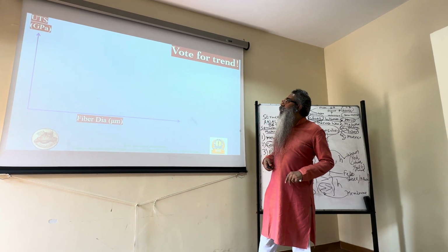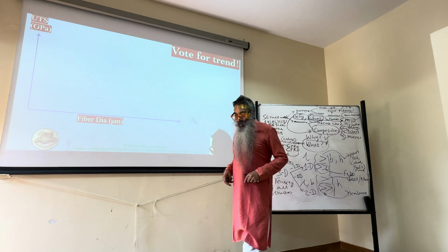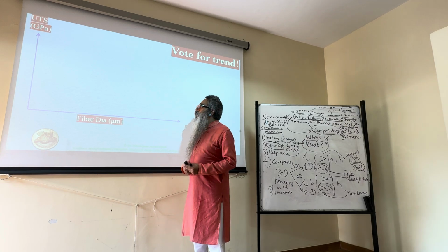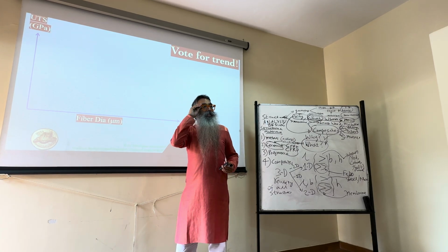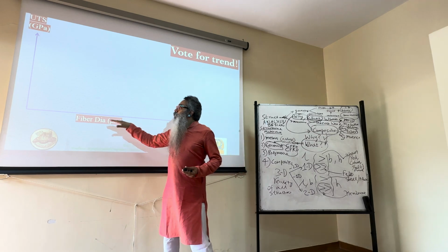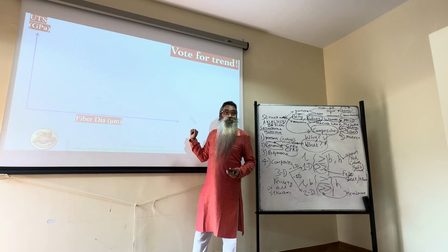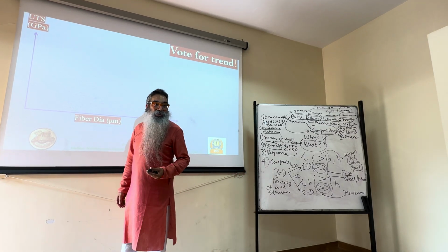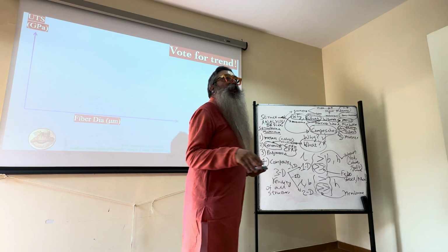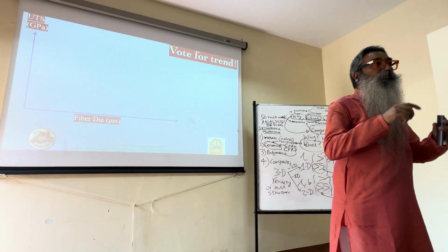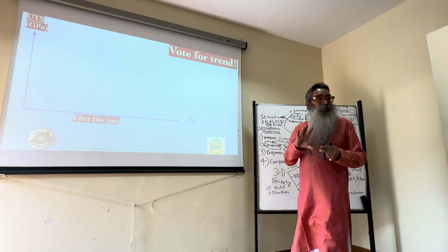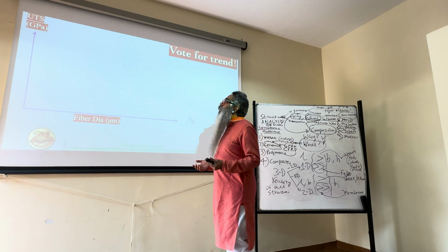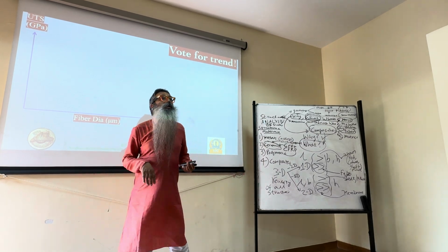Okay, so let's move from a qualitative question to a graphical representation of it. It's the exact same question that I asked at the end of the last slide. I am plotting the ultimate tensile strength on the y-axis versus fiber diameter on the x-axis. I'm not changing the material, and as you said, only the force at which failure occurs changes. The stress at which it fails should not change, right? So in other words, how should this particular curve look?